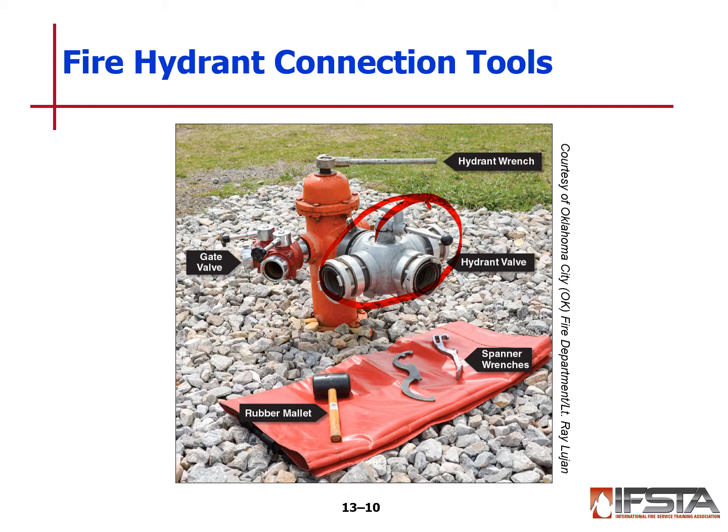All right. To operate the stem and the nut, a hydrant wrench. These wrenches are designed for the specific nut on top. It's usually a hex head style nut. In theory, you could put a pipe wrench on this and operate it, but it's much easier to use the wrench that is designed for it. And the other key to this is not just anybody can turn this on. The water company can turn it on with a wrench. We can turn it on with a wrench, but somebody just walking up and down the road couldn't turn this on very easily.